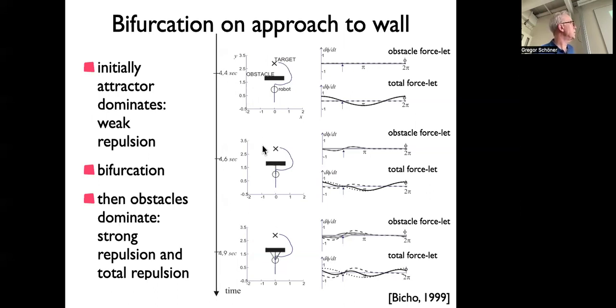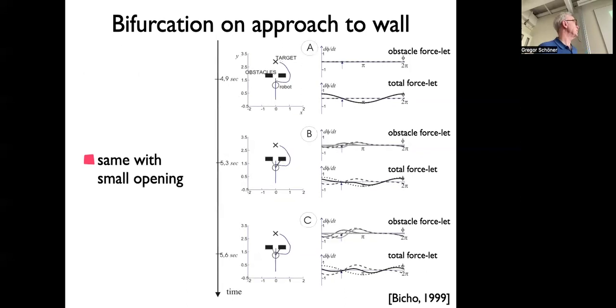And just between, this is only a target contribution, no obstacle. And then there's a little bit of an obstacle contribution, but the target contribution still dominates, still an attractor with negative slope here, but it's getting flat. It's closer to the bifurcation. And now it has happened. Now we have a positive slope here, a single repeller, and there are two attractors on the side, which correspond to turning around. So I'm inviting you to really look into that in your essay to really understand it.